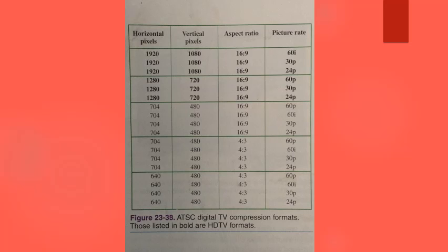The Moving Picture Experts Group developed the MPEG-2 image compression standard to increase the amount of video data transmitted in an HDTV system. By compressing the broadcast video data, more information could be broadcast in the same amount of bandwidth. The MPEG-2 compression technique can reduce the image information as much as 97%, but an average of 50% is typical.